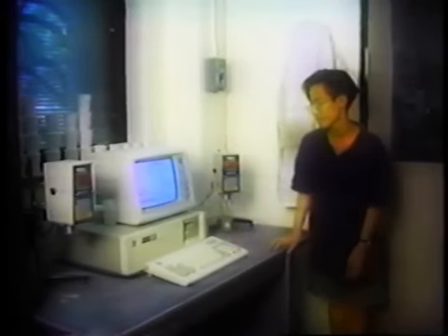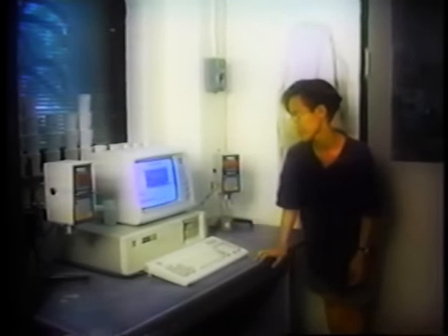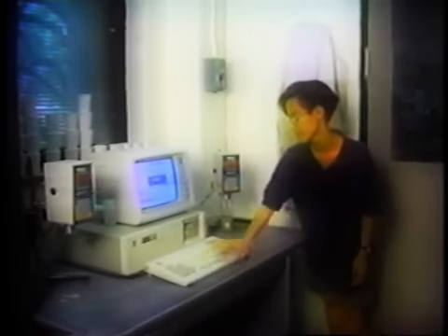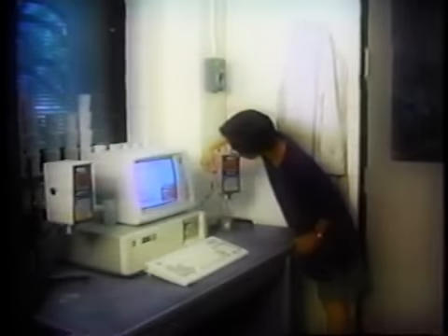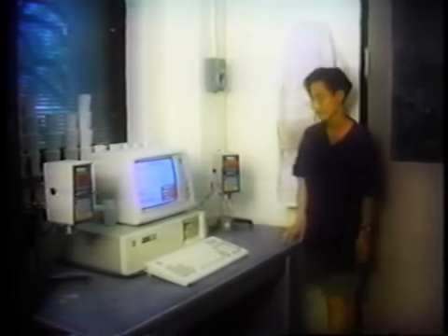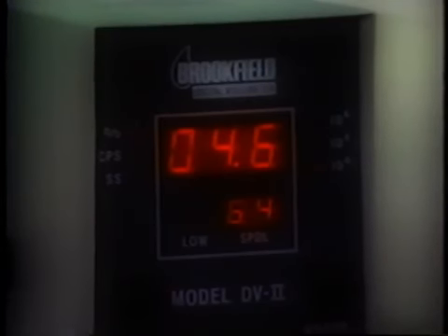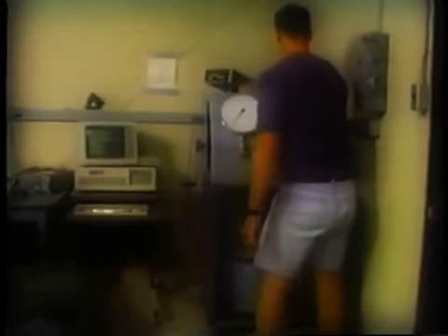Water is a liquid with low viscosity and a low initial resistance to flow. But concrete, mortar, and fresh cement paste have much higher viscosity than water. Vibration is often used to overcome this resistance in concrete. In the lab, fluid properties of cement paste can be measured with this Brookfield rheometer. Researchers use larger equipment, such as this Tattersall rheometer, to measure the properties of mortar and concrete.